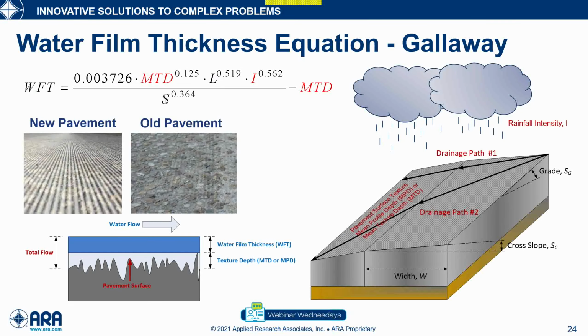Right. So when you cannot avoid those transition zones on the cross slope, the recommendation is to control the grade. FDOT actually has a recommendation to have at least 0.5% of grade on these zones. So that is what you could do. The other strategy you could use is to put some signs there to prevent drivers from increasing their speed in those particular zones where you have increased risk of hydroplaning.